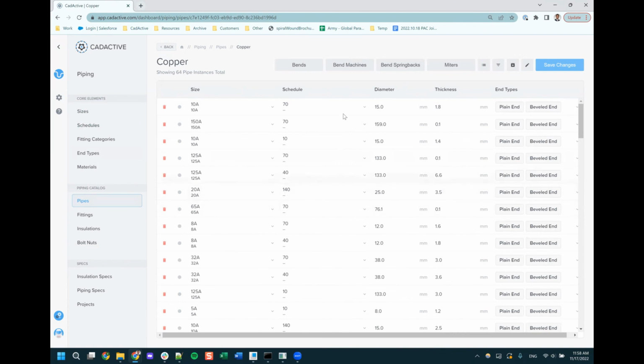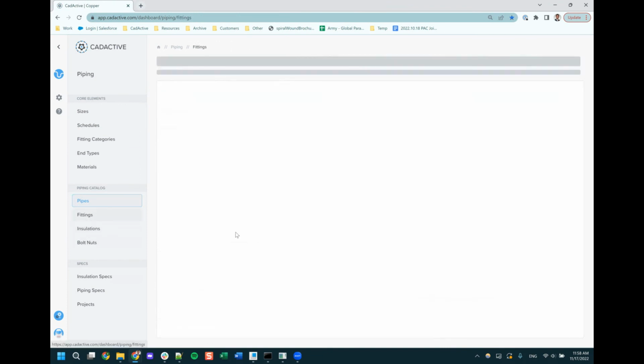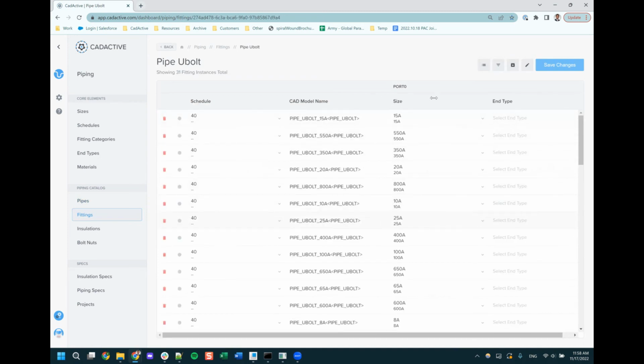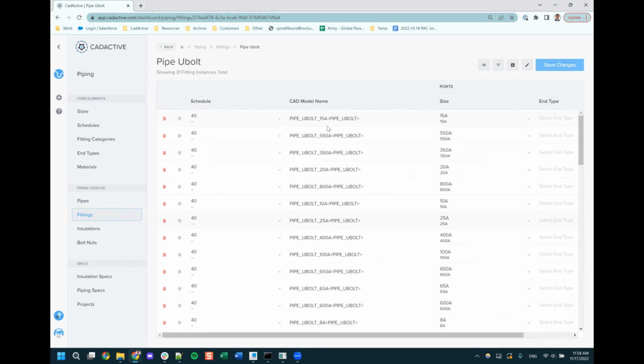Okay, so basically it's like family tables, say for Mil Handbook 5 hardware, but this is for piping. Yep, you're exactly right. The pipes are defined on the fly by Creo, but the fittings do need an actual model too. So this is where we have our CAD model name. And as you can see, based off of the naming format here, these are literally family tables inside of Creo that Spec-Driven is just calling those instances in order to place it in your pipeline. Cool.